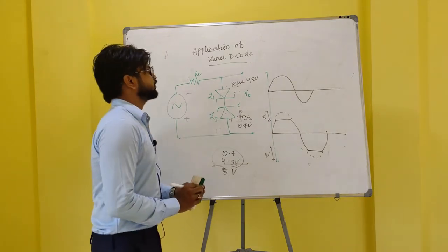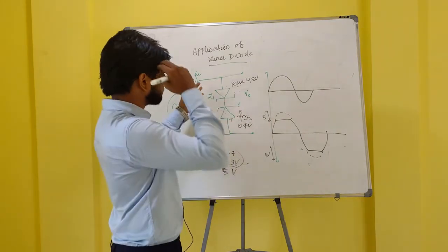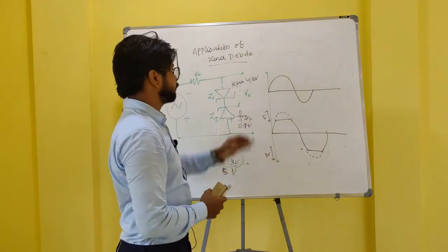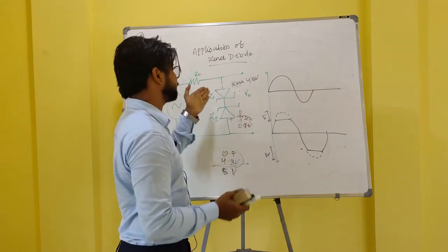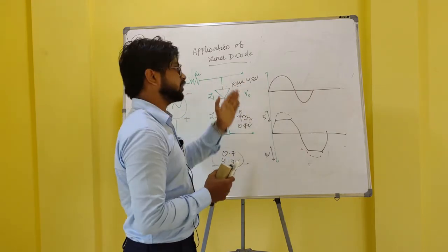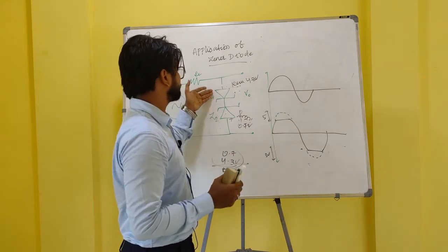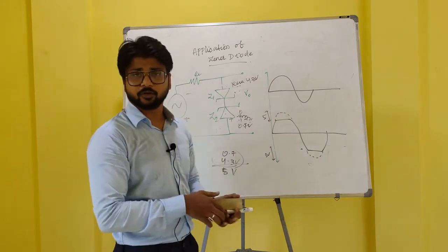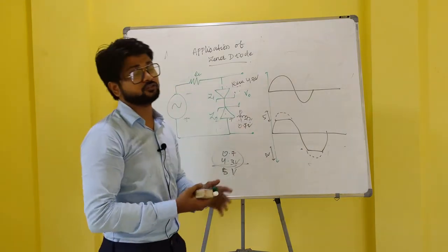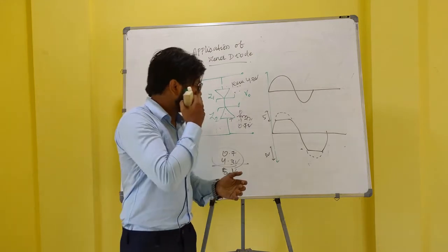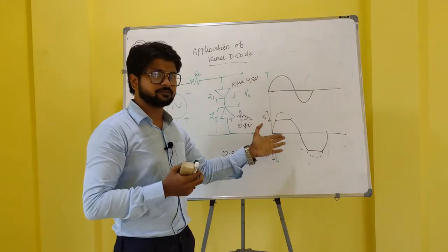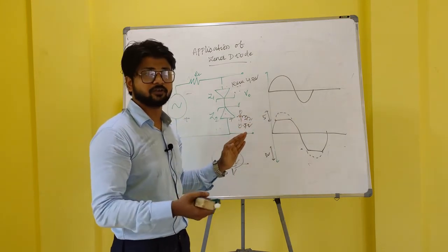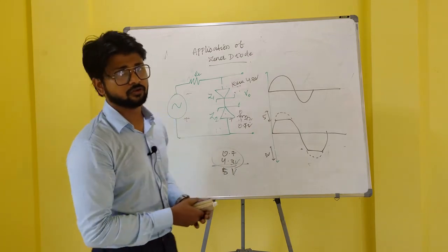cycle. So we could say that this double Zener diode clips the input signal from both the sections equally if the avalanche breakdown and the Zener breakdown voltages are equal for both the diodes. So let us observe this in Multisim 14.1. It's a simulation software which we discussed in the first lecture, and we'll see whether these theoretical concepts hold good in practical terms and whether these kinds of outputs are observed if we do it in Multisim or not. So let's see.